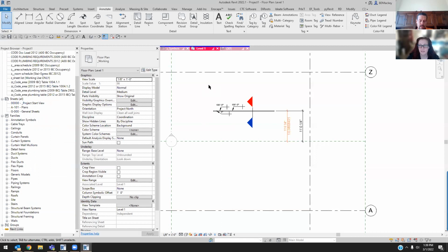If somebody else had reloaded it and then they synced, then you theoretically, when you synchronize, should see it as well, theoretically. I do not see that happen all of the time. So for me, if I want to make sure I'm going to print and I need to see the latest of what they did, or the same thing with my export, if I publish my Revit file, I always want to make sure those links are all reloaded before I go through and do any of that too.